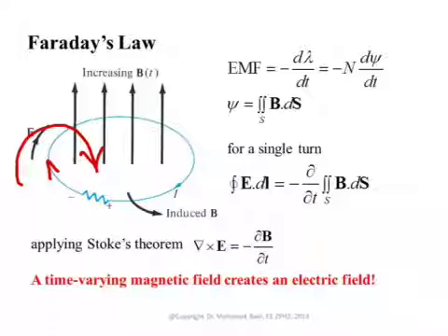Now, even if you take this resistor out from the circuit, you will be able to measure a voltage difference between these 2 points. This is what's called E dot dl. So E dot dl is simply to carry out an integral around this contour, and then you'll be able to see its value, positive or negative. Now, one word of warning: if I select the normal to the loop in this direction, then dl has to be taken according to the right hand rule. This is why this voltage here, even though it is shown as plus minus, is negative with the direction of dl.